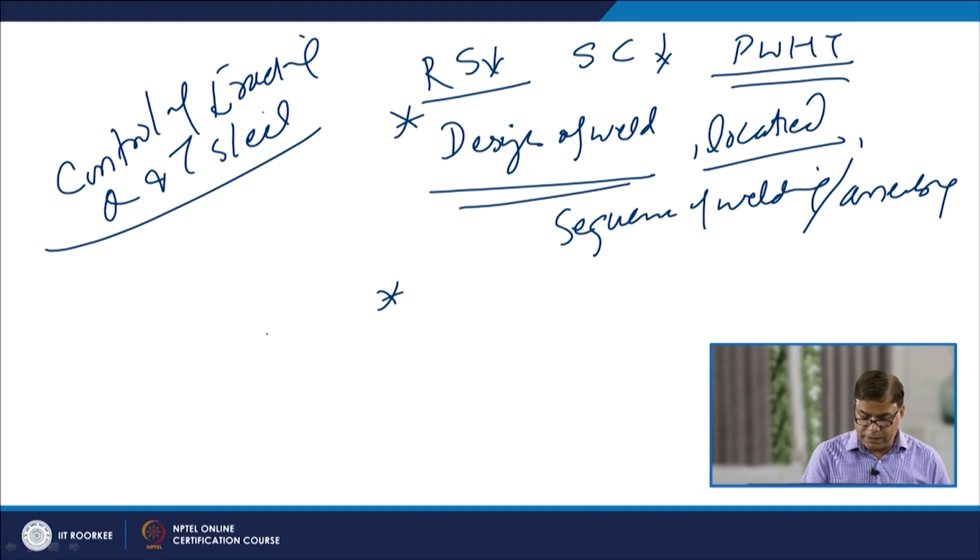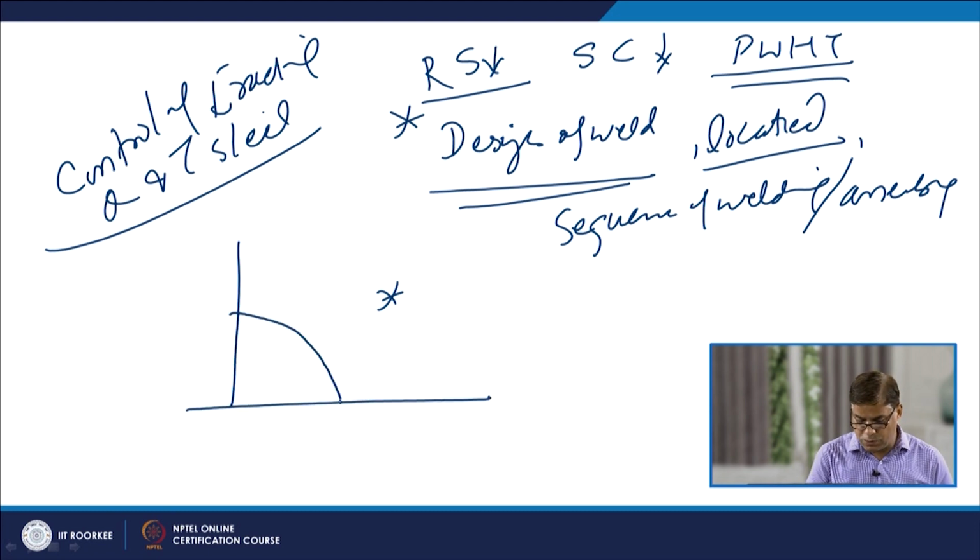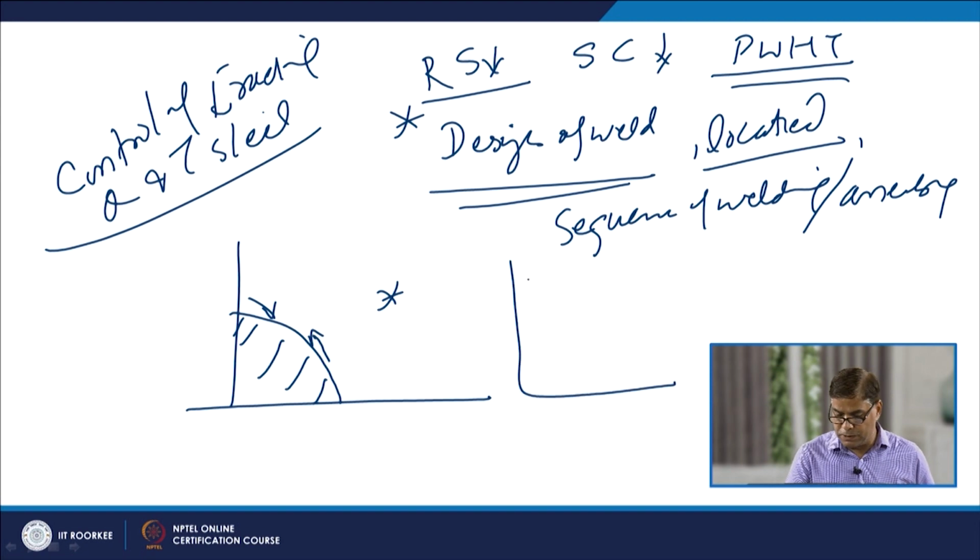minimized. Further, when the weld metal is deposited, if it has a convex contour, because of the contraction it sets in compressive stresses at the surface, as compared to the case when the weld joint has a concave bead geometry, and contraction in this case sets in tensile residual stresses.